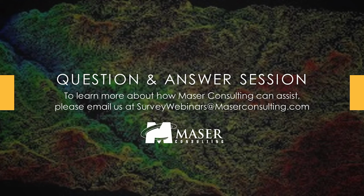If you're only looking for planimetrics, then LiDAR is overkill. You're better off using a photogrammetric approach. But aside from that, whenever I can, I am using LiDAR.